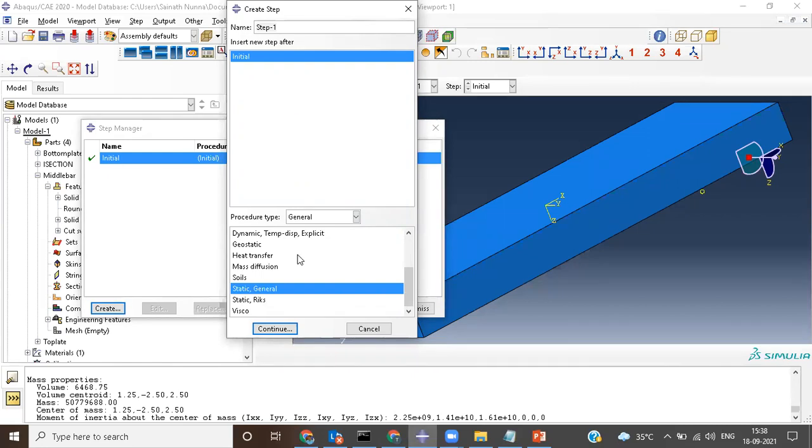Now today you have learned how to create a material with just a density in the general density that you are creating. Then after creating that material, you apply it to your part and measure the weight of the part. Then you have to check whether the weight matches the physical weight or not.